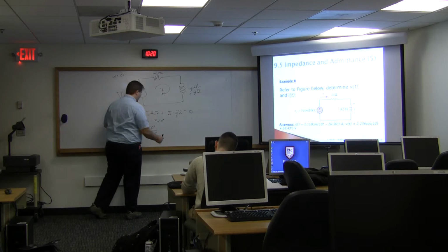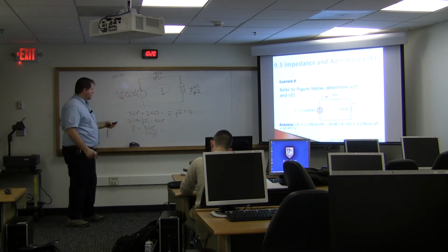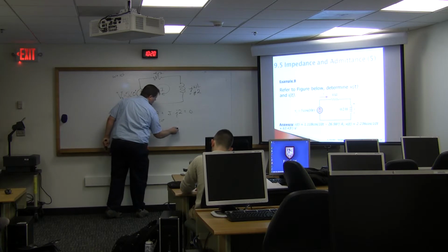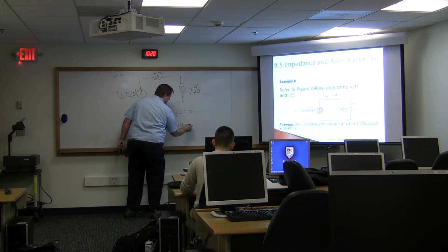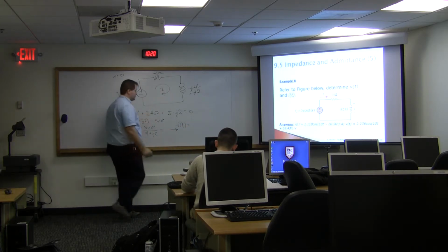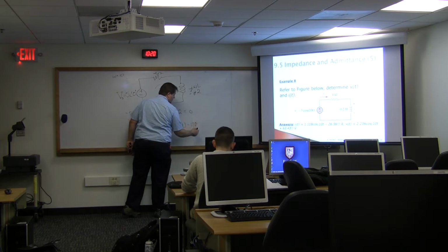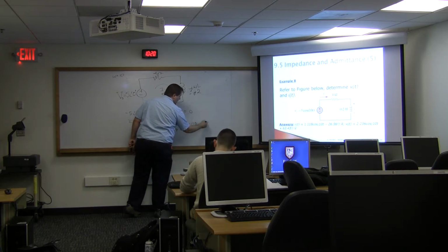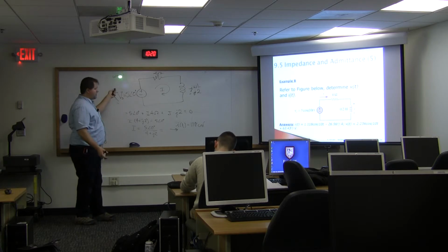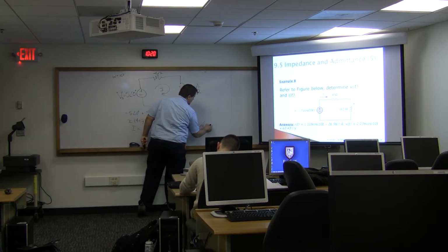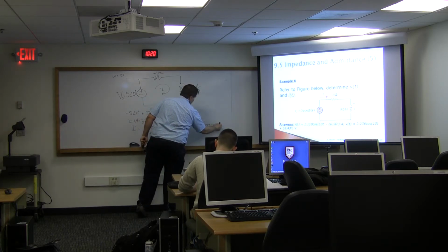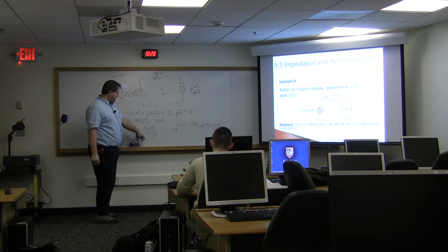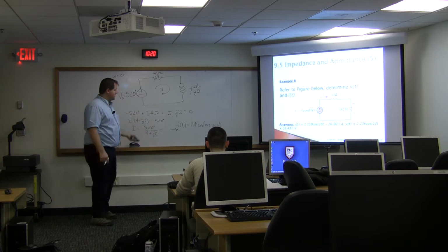Since I already have the answer written down, once you've done that, you are going to go back into the time domain, right? Shift it back to the time domain so it becomes little i of t, and then the magnitude of that, which worked out to be 1.118, is times the cosine of omega t. Omega never got lost. We had it right here all the time. So that's just 10t, and then the phase worked out to be the -26.56. Which means this guy down here must have had a phase of 26.56 degrees, because then it's 0 minus 26. And so that's I.